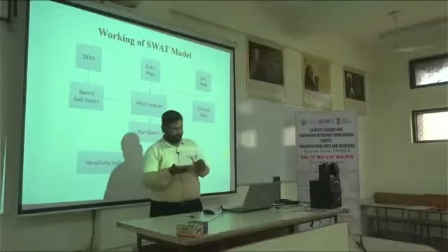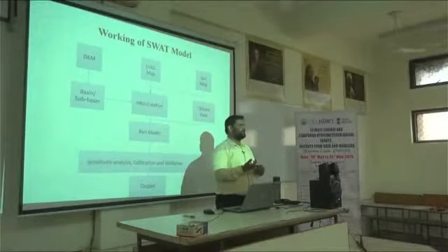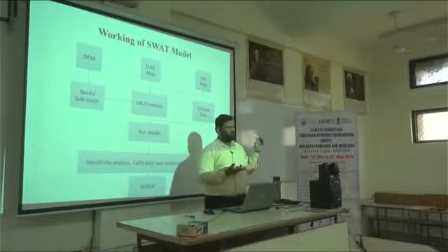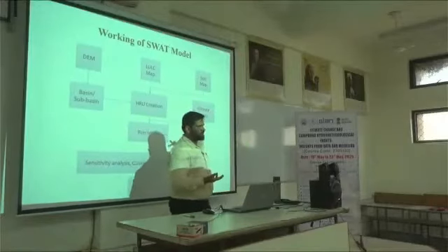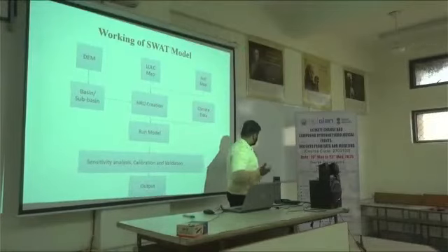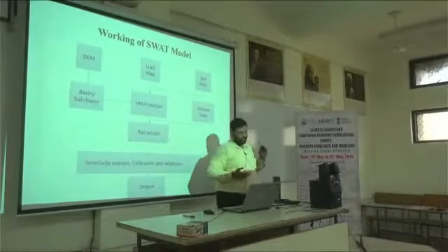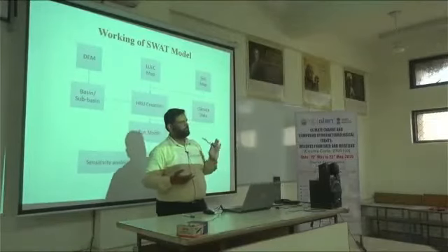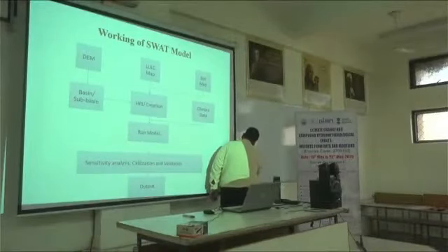If you don't have wind speed, solar radiation, and relative humidity data, only rainfall data and the minimum and maximum temperature of the day are sufficient to simulate the hydrology of your catchment area within the SWAT model. Keep in mind that you should have at least rainfall and temperature data, in the form of daily data: daily rainfall and daily maximum and minimum temperature.